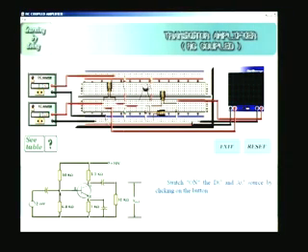You can see there is a breadboard here, and you have the transistor BC107, R1 33K and R2 6.8K, and this is the RC which is 3.3K, and you have RE 1 kilo ohm. You have the coupling capacitor here, and another coupling capacitor here at the collector, and this is the load resistor which is about 10 kilo ohm here, and this is a bypass capacitor that you see.